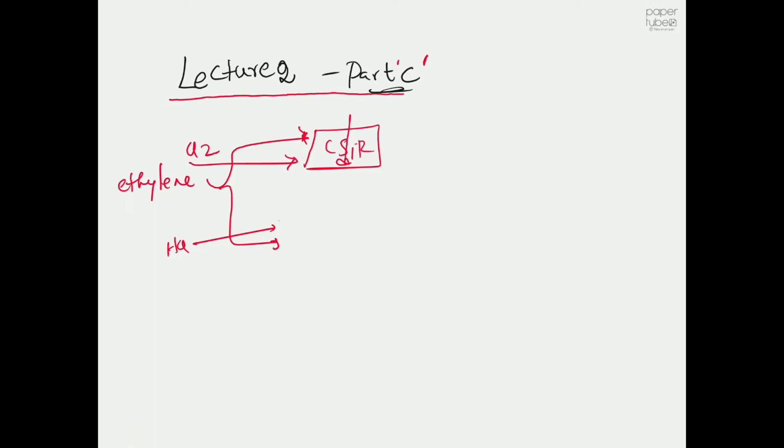and then the oxychlorination we will perform in a catalytic reactor. Here we will model it like a plug flow reactor. So both the direct chlorination which we are going to perform in a CSTR, and also the oxychlorination reaction which we are going to perform in a PFR, we are going to use catalyst, which will be CuCl2 catalyst. And I already mentioned the process conditions.